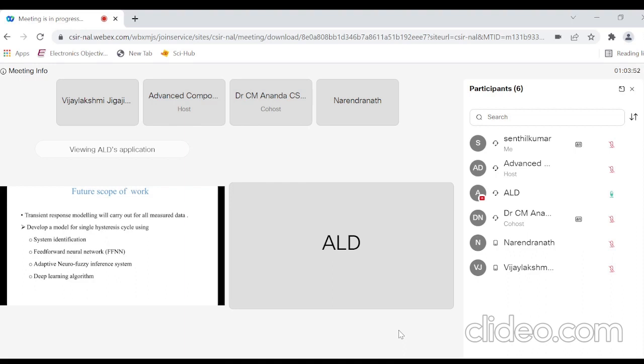Okay. Now you understood that for a particular blimp application, you have taken the 0.6 diameter. Now why did you conduct experiments up to 25 hertz? In a blimp, it will not go beyond 0.1 hertz. Actually, we are conducting at different frequencies for the hysteresis loop, so that's why we conducted that experiment. Now you mentioned 0.6 is taken for a particular stress. When you increase the frequency, definitely the number of cycles to failure will come down. In one of your tables you mentioned 25 hertz failed in 2000 cycles, which means fatigue life has come down.